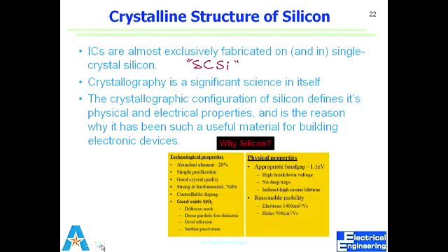Right, so why silicon again? There are a number of things apart from the good oxide. It has many uses. It is abundant, easy to purify, has good crystal quality, and is a strong and hard material. Doping can be controlled. Physically, it has a band gap which is easily used in electronic devices. What is band gap? Distance between valence and conduction band.